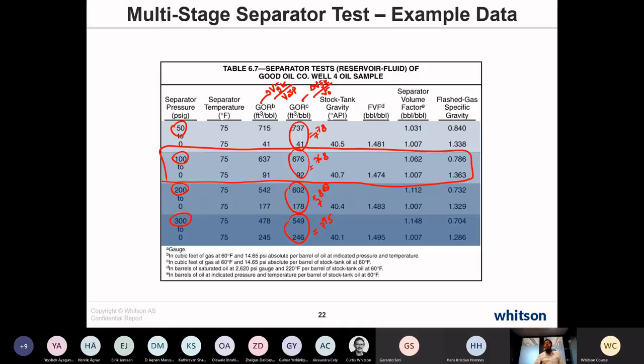And that's what Curtis was mentioning, that for the flash procedure, when Muskat and McDowell introduced it in 1949, the main aim was to find the optimum separator pressure and temperature that can give the maximum liquid yield at surface. That can be easily done with an equation of state model.